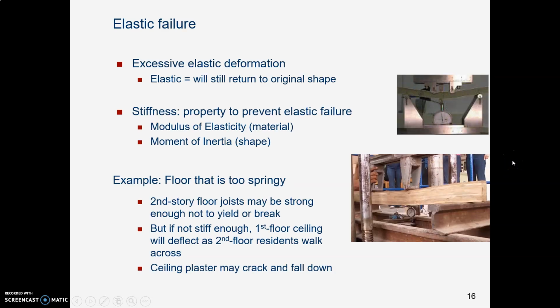So elastic failure. Okay, it's a failure because the object is not functioning as intended, but it's not disastrous. This is the kind of failure you find if you're walking on the second floor of a building and they have used joists that were not stiff enough. They were strong enough so they're not going to yield and they're not going to break, but doggone it, they're awfully springy. It's like walking on a trampoline. That is a kind of failure because nobody likes that. It makes you feel creepy, like something might happen here.